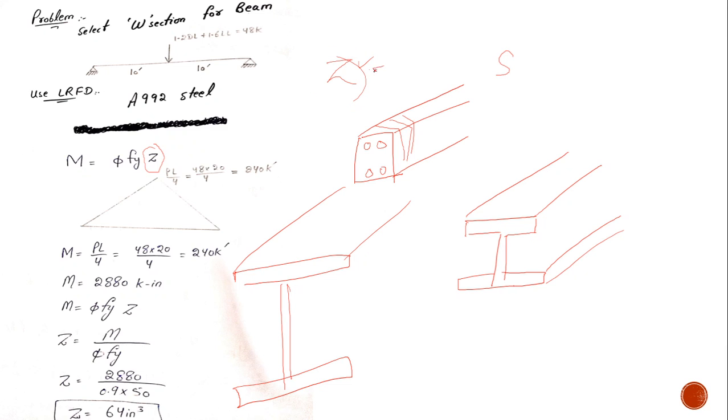It is simple. The Z is obtained by dividing the moment of inertia, or second moment of area, by the neutral axis distance, or simply C. So its unit is inch cube, not cubic inches. Sorry. So let's first solve a question, and we are given a very simple question.